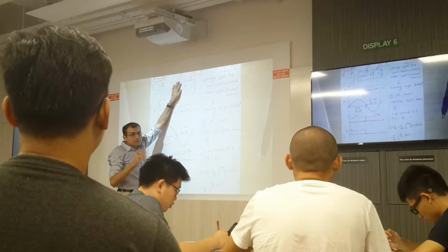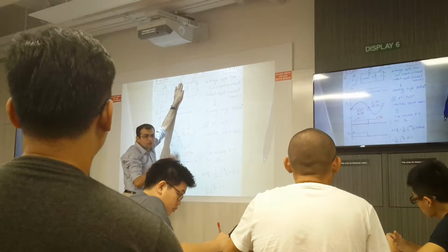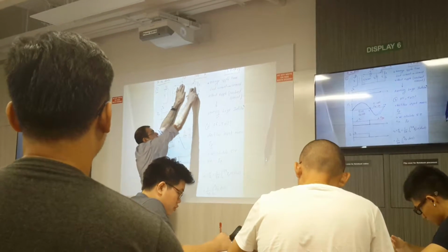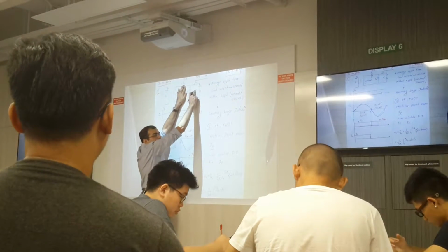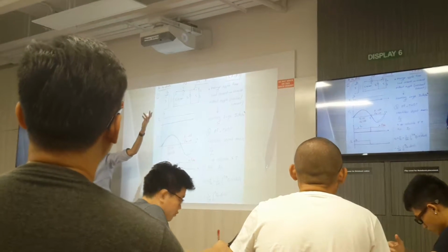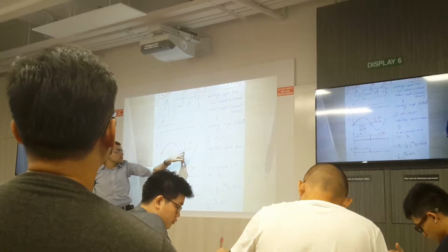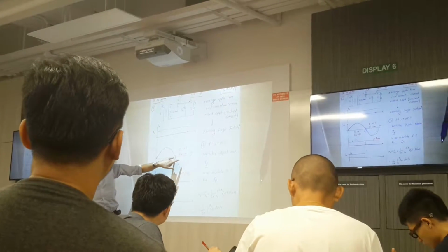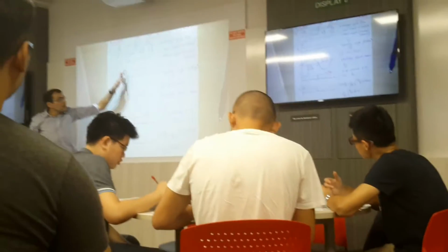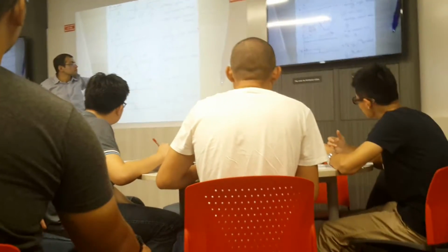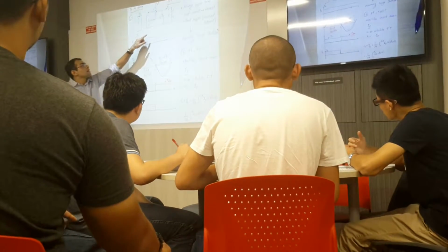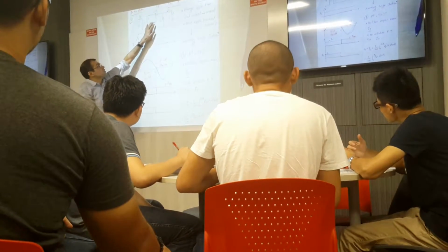So Dm becoming on is not because of the voltage. The reason for Dm to become on is the current of the inductor which is flowing and wants to continue flowing. So this will force Dm to become on. So during this from pi to 2 pi, D1 is off because of the negative voltage which we have, and Dm becomes on.